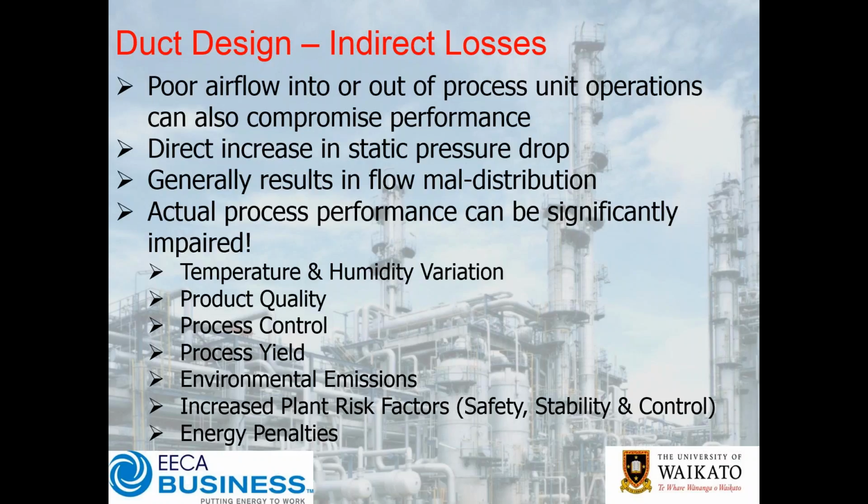You can run up against environmental emissions problems if your cyclones aren't working correctly because they've got poor airflow distribution, or your fans have been incorrectly matched to your cyclones. You can then end up with excessive emissions. Certainly, if not on regular running, at startup and shutdown can become an issue. Ultimately, what all of this leads to is increased plant risk factors, be it safety, stability and control.